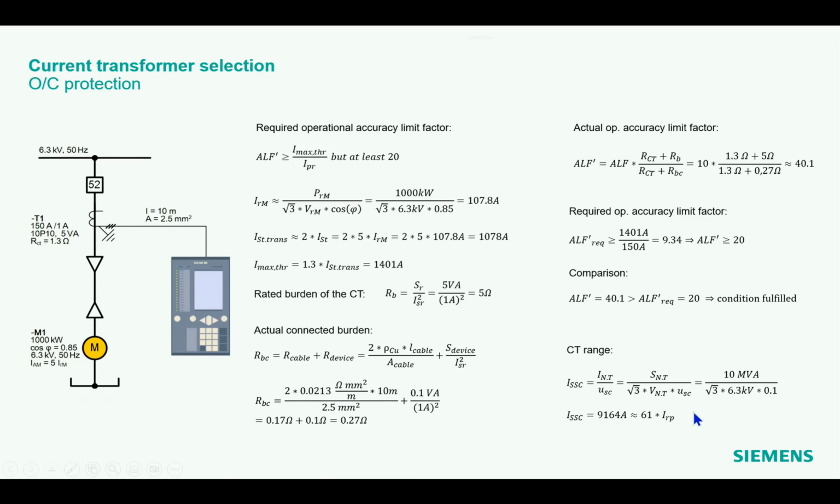For differential protection, especially for a transformer, this different grade of clipping can be a problem. Therefore, I mentioned this here, because anyhow, we have different levels of current transformers, voltage levels, and nominal currents of the current transformer. So here you could have this problem, and you need to keep an eye on that. Another thing you should keep an eye on is the thermal capacity of the current inputs.